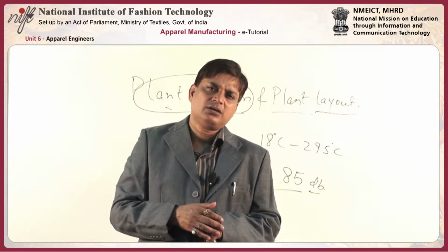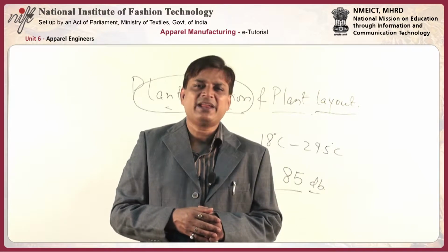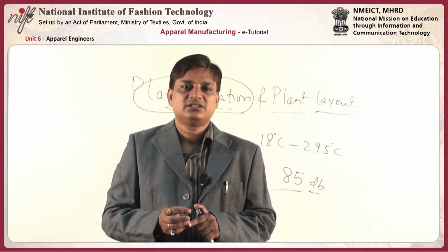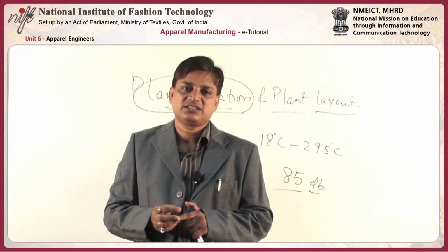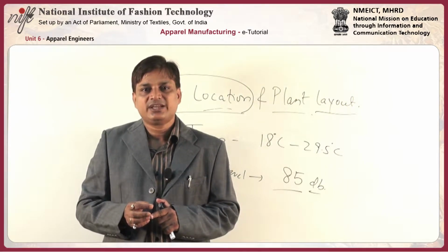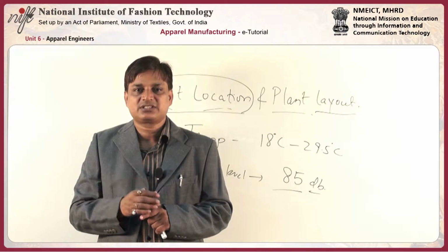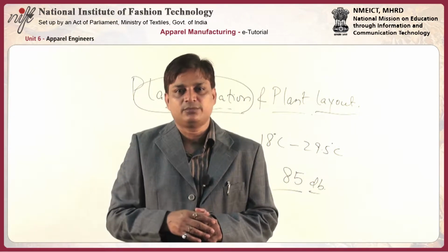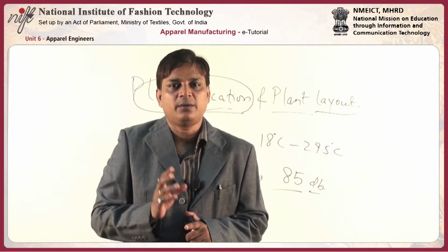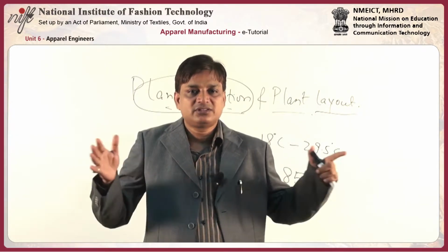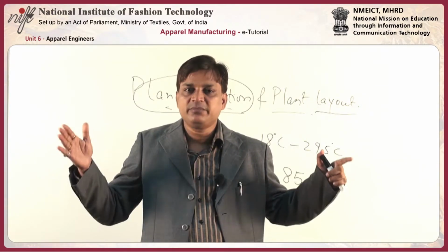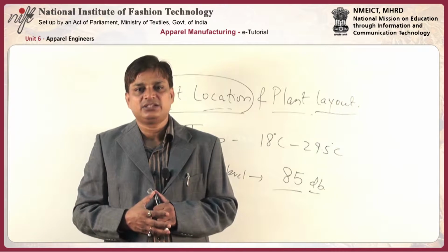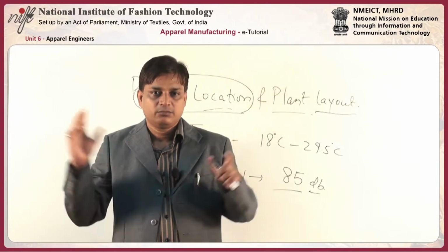Now we are moving on to the planning of each independent section. It is important to know some points that are common to the layout of each and every section. There should be at least two exits, as I have discussed, on the floor, and the exits should be on opposite sides of the room. The exit door should have a minimum width of 36 inches, that is 3 feet. The floor on each side of the exit door should be level on both sides.